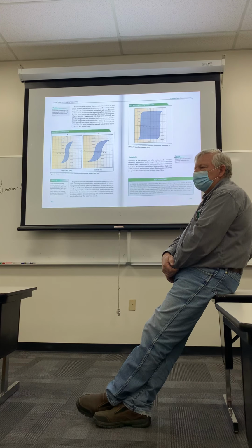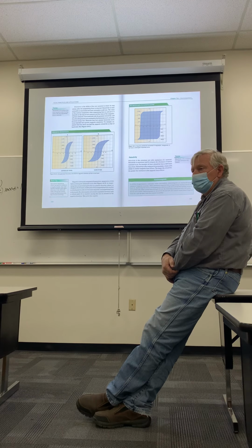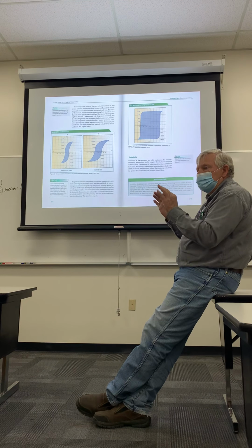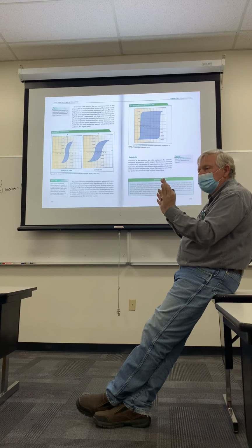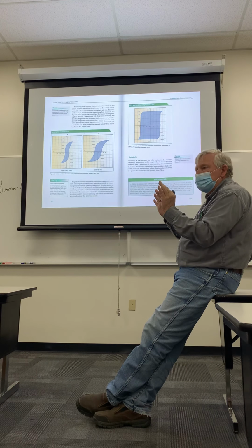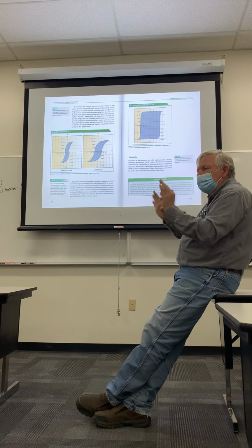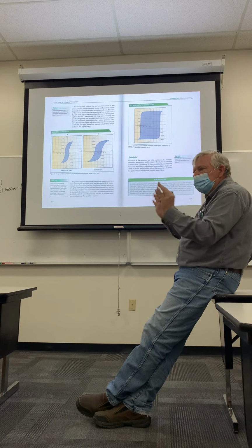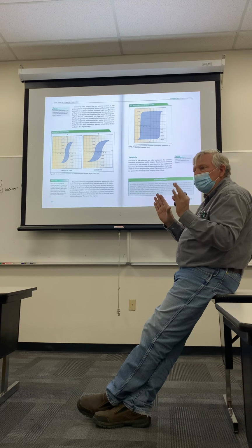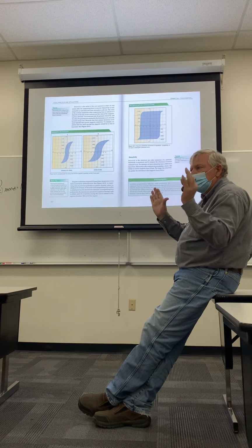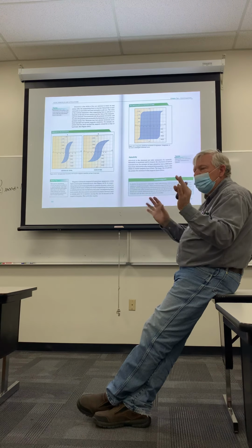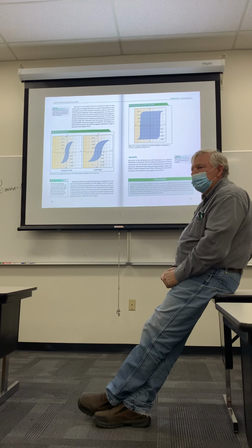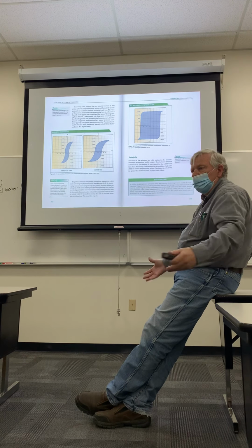I was thinking specifically of something like a speaker, because they use those magnets to move those cones on a speaker. So if you have something that is really slow, has high retentivity, you're not going to get the subtle movements in those speakers that you need to get the right kind of sound. So you'd want something with a relatively low to non-existent hysteresis curve. On, off, on, off. It can do that over and over, millions of times before it wears out. So there's applications for both ways.